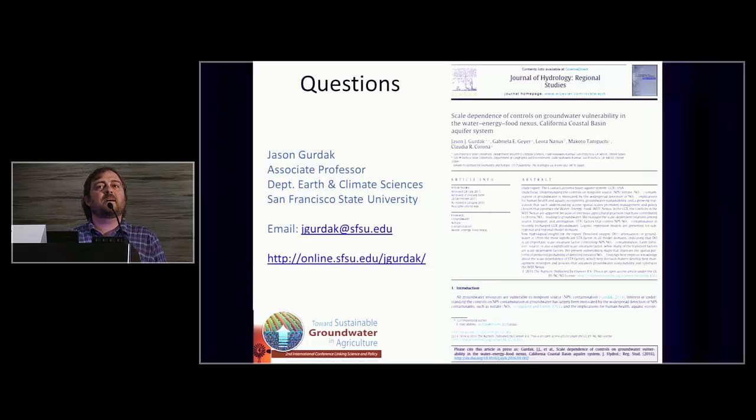Yeah, that's a good point. We didn't actually look at that, so we didn't compare screen depth to DO or redox conditions, but I know generally you would expect to become more anoxic the deeper you go in a groundwater system. I know Pete McMahon and some others have looked at that, vertical gradients and redox conditions, and in general, in many systems in the U.S., it gets more anoxic the deeper in the aquifer that you go.